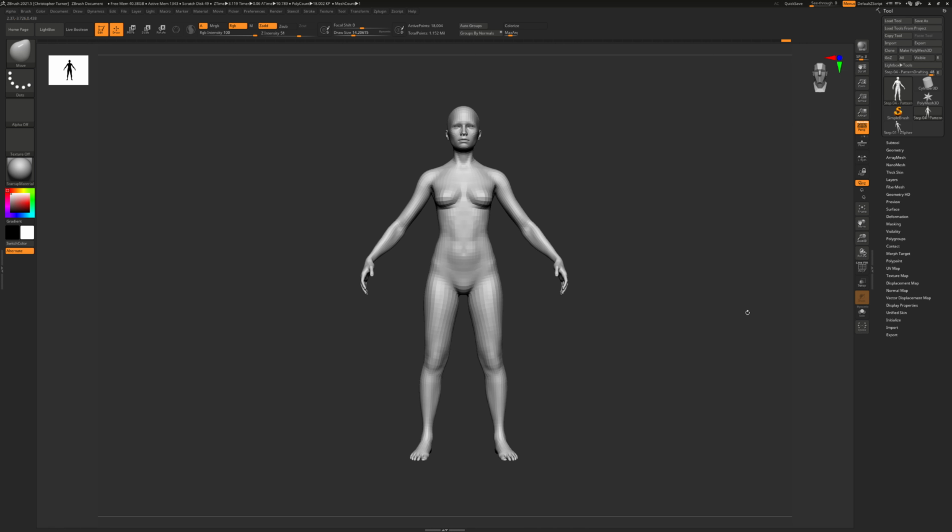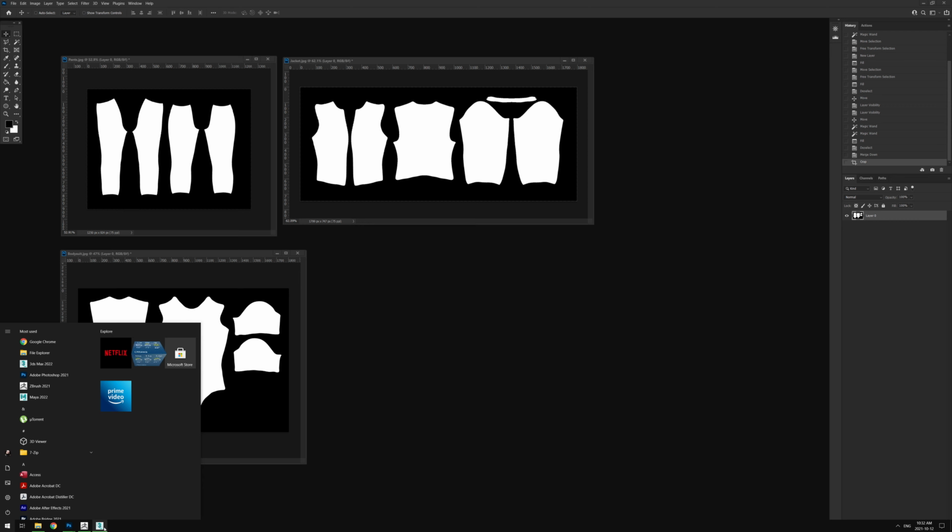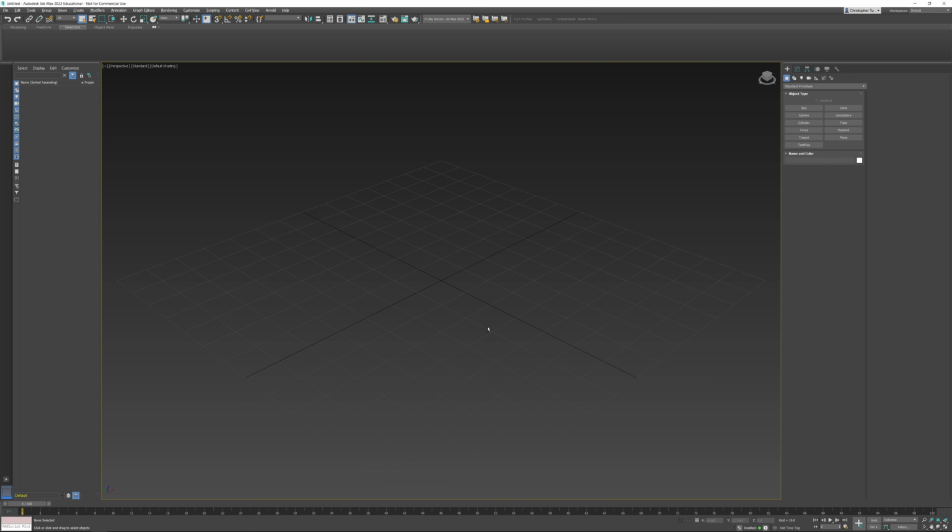Now, if you look at the export settings, it is going to imbue some kind of scale on import export. I don't want to manipulate that because those numbers are really kind of skewed, that 82 with 9 decimal points. And what I want to do is go into a package like Maya or 3ds Max, and set the scale of my character correctly here, as well as make sure she's standing on the ground.